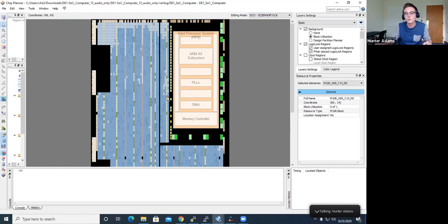While you're working on finishing up Lab 1, pull this up for your Lab 1 project and just look at the total utilization of the FPGA. You'll see that it's not being utilized very much. It'll give you a point of comparison for Lab 2 when you are really trying to fill this thing up.